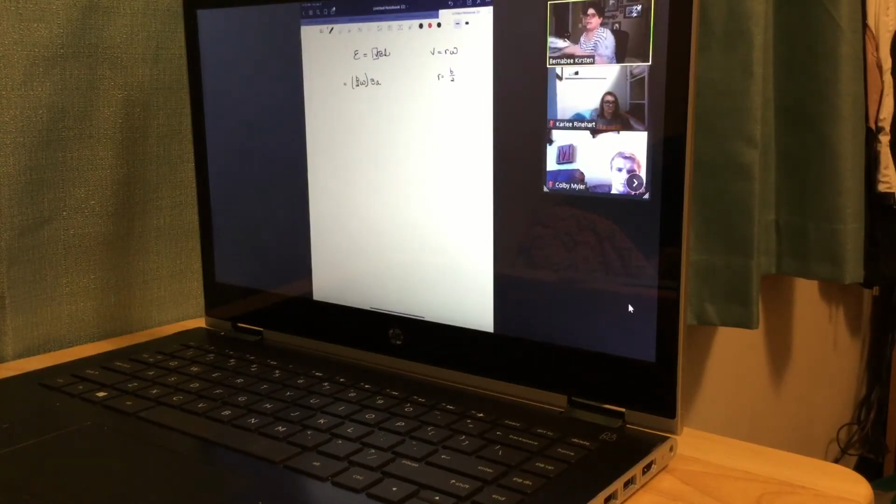Okay, next thing. This isn't always going to supply a nice constant voltage. It depends upon where it is in its rotation. So right now, I'm going to say my angle is 0. We're going to increase it to 90, and as I increase it, I increase my voltage. And then we're going to decrease the voltage as we go to 180. Somehow I need to take into account that angle, and that angle is going to depend upon the time that I look at it. So this is where the sine omega t comes from. Omega t is equal to our angle.